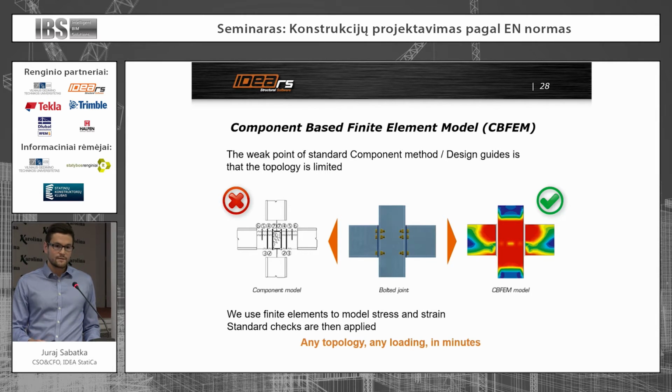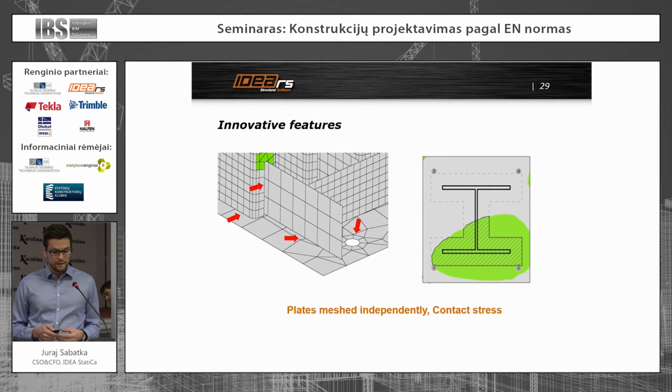So we replaced the first step with finite elements. We use finite elements to determine stress and strain, and then we apply the checks. This enables us to get rid of the limits. You can do any topology, any loading, and in minutes.